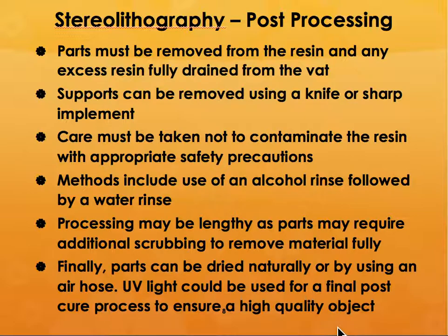But you should make sure that you are not contaminating the resin, with appropriate safety precautions, because in case the laser shines even by mistake on a free part of the resin, then it hardens, and those hard layers are left behind in the resin vat. You do not want that kind of a hard piece coming on top of the part that is being built. If that happens, then the whole part is scrapped.